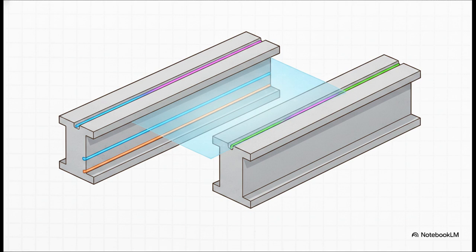But if it drops into the web, you have to account for both the flange and the web in your compression block. And if you happen to be using unbonded tendons, where the strain isn't perfectly compatible with the surrounding concrete, IS 1343 gives you a completely separate table, Table 12, to determine your stress based on the span to depth ratio. The beautiful thing is, the limit state philosophy remains completely consistent no matter the structural form.